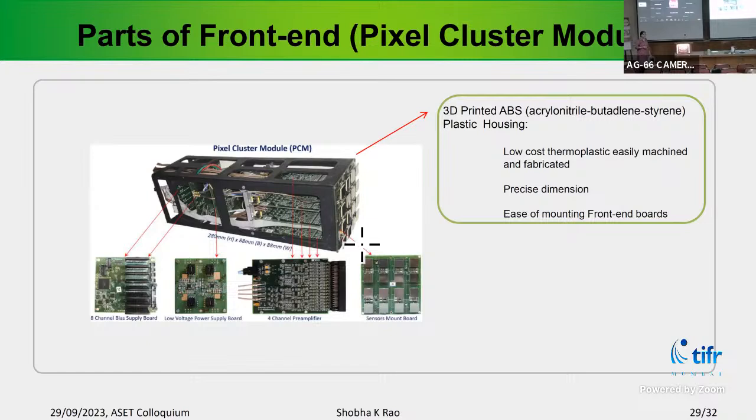My question is, how do you get such a fast rise time? Is it just because you are limited by your amplifier? If the thickness of the silicon is large, then you would not get that fast rise time at the output. The SiPM typical rise times are a few nanoseconds.